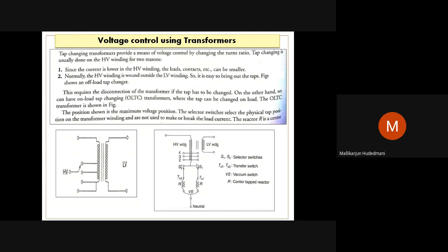That means the drop in voltage due to the inductiveness of the system, that is, reactive power only. We are trying to compensate the reactive power by taking care of whatever drop has happened. That drop you are substituting or compensating by adding taps or a voltage into the system to make it as per your requirement. This is the facility being noticed. How is this mathematically viewed?